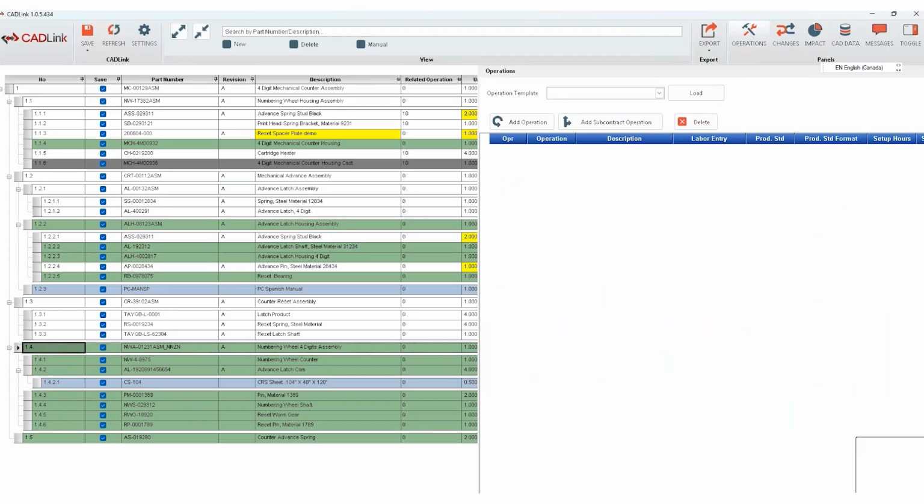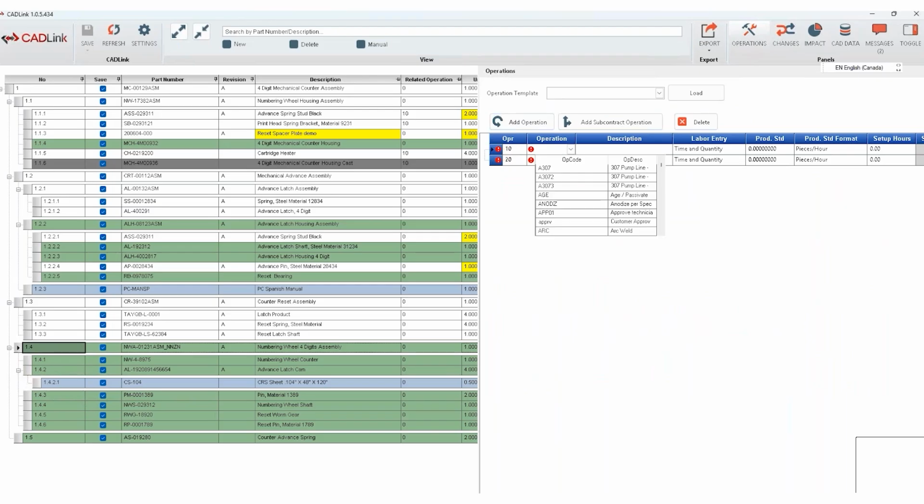What I can do now first is choose a parent of what I need to populate the operation sequence to. Would it be a top level? Would it be a sub-assembly? Would it be a part with raw material? Does not matter, it will work identically. For the purpose of the demonstration, what I'm going to do is use this sub-assembly here. And what I can do now is to add the sequence operation that is needed to create this sub-assembly out of the 6 children. And to do so, I'm able to add operation step 1 by 1 as needed. Step 10, step 20, I assign the work center and assign any of the additional required operations information here.